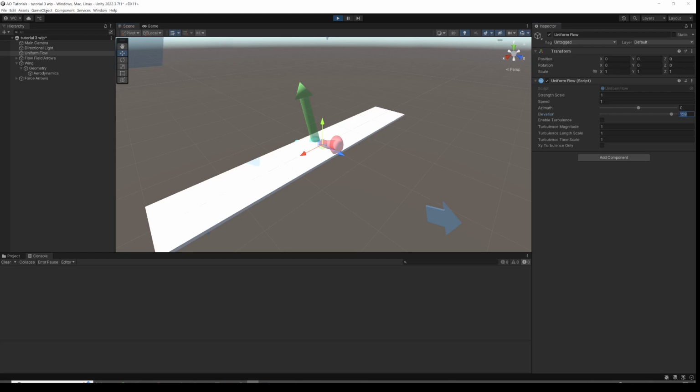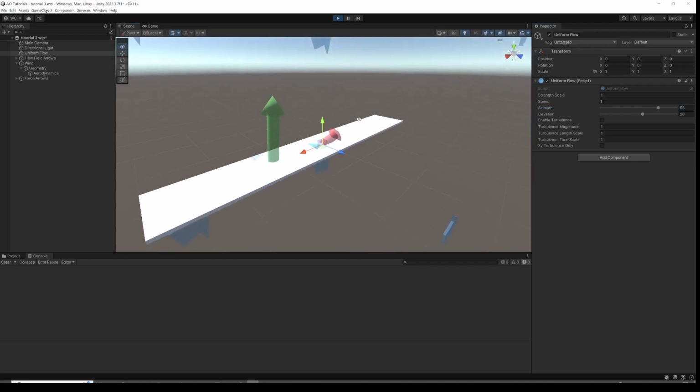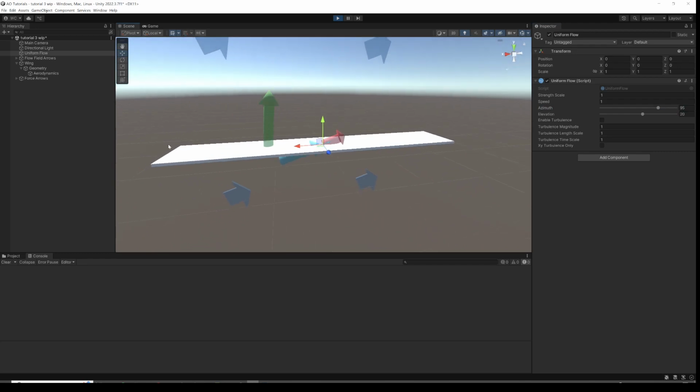One other thing we can look at is what happens to that aerodynamic center when we have a side slip or azimuth. So if I vary this, we can see as we get round to flying sideways, that aerodynamic center has moved out to there. So it's now roughly a quarter of the way back, or in the chordwise sense this way. And so that's the correct position.